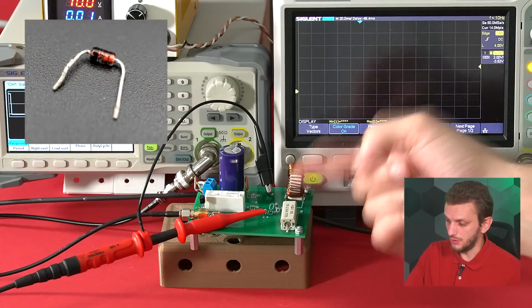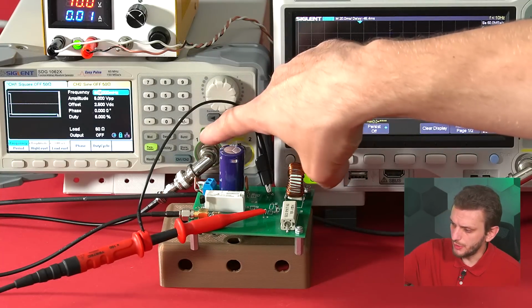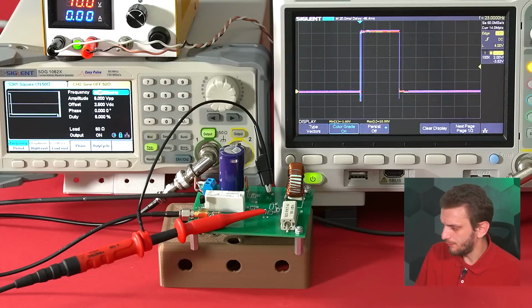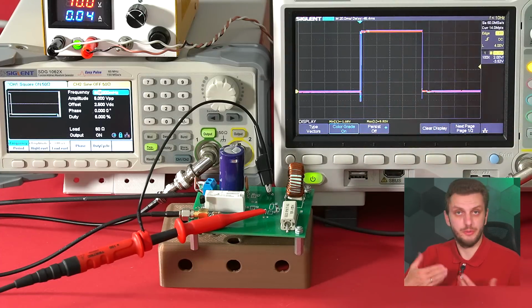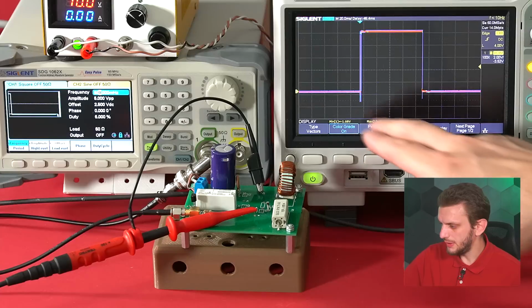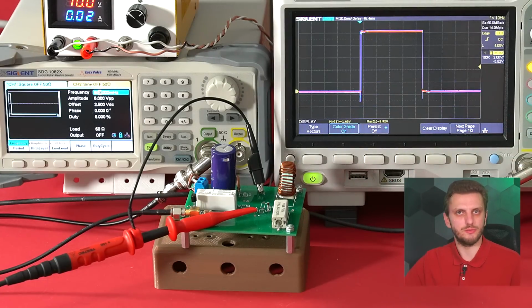So I added the 1N4148 diode in parallel with our load, and if we turn on our switch, we can again see negative voltages at both turn on and turn off because of the switch bouncing, but the minimal voltage is limited to about minus 1.7 volts. So this is perfectly normal for this diode when a current of around 700-800 milliamps is running through it.